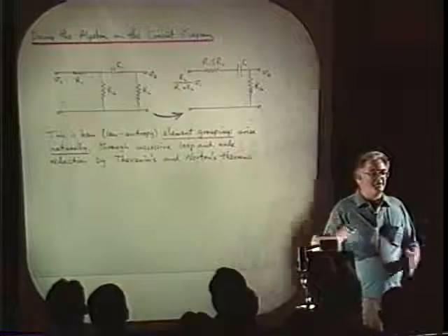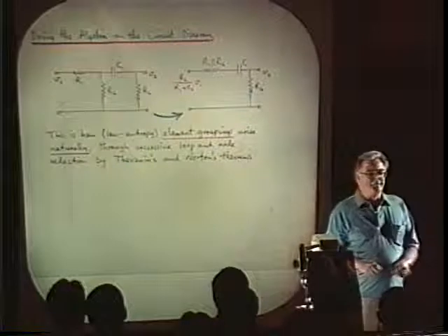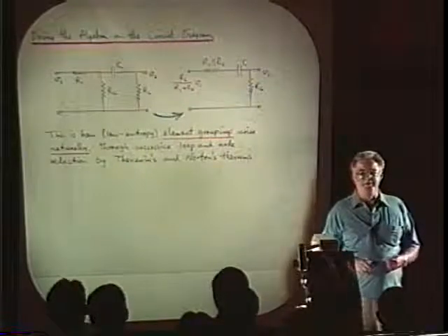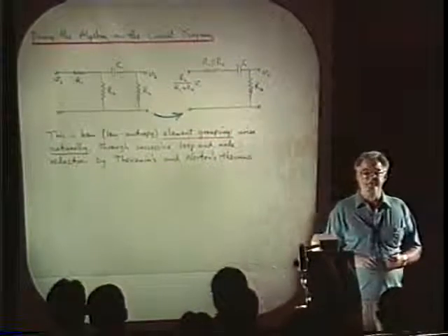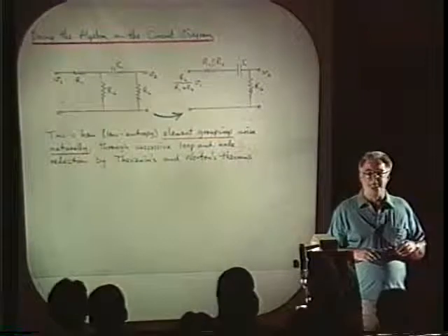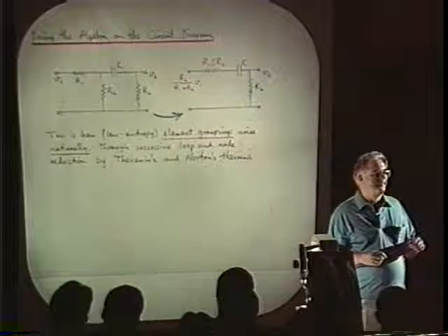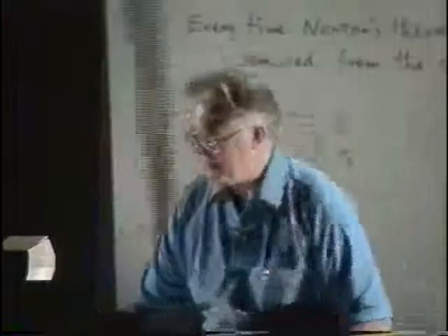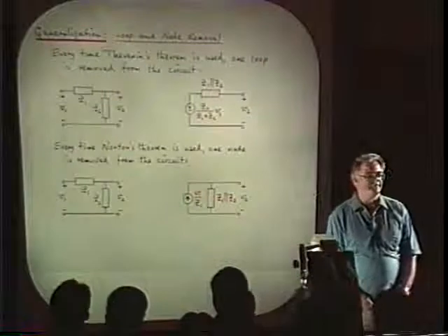And if I were to ask you, who've been out there a long time, how often do you use those theorems in your work? I would suspect that the answer would be not much. For that very reason. You were very adept in applying it, but no one bothered to tell you why it was worth doing. The real value of Thevenin's and Norton's theorems is every time you use one of those theorems, you reduce the number of loops and nodes by one.